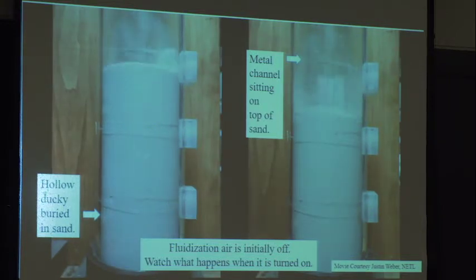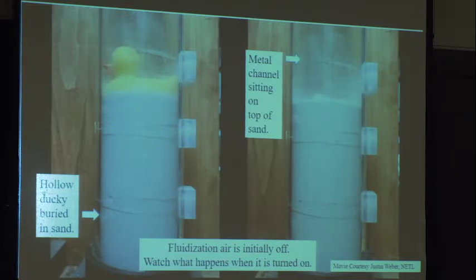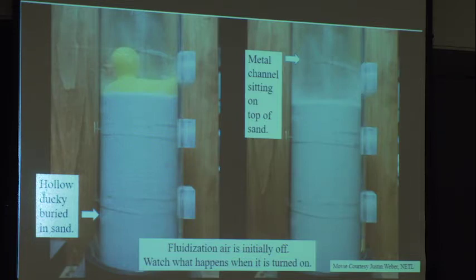There we go. Okay. So you see the metal just drop down in, and if you're patient for just a second, boom, up comes the rubber ducky, right? And it will float on that surface. Now this is fun to watch, but it's practically extremely important, right? Because in a fluid bed, you can sort materials out based on their densities, right? Some will sink and some will rise to the surface.